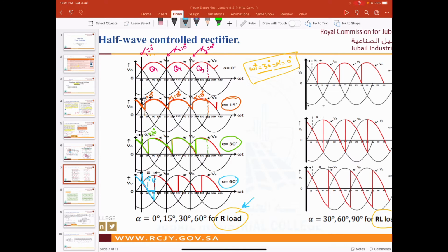Now this is a very good question, and its answer is very clear, because we cannot go negative because this is a resistive load. It is not an inductive load. It will not charge anything. So this is a resistive load, so it will go 0 up to the next firing angle, which is 60 degrees, right? Then we will go up.